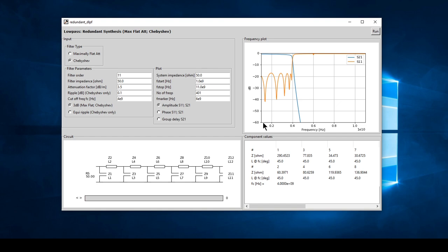You can vary the start and stop frequencies of your frequency plot. In this case it is 1 gigahertz and then stop at 11 gigahertz. The number of frequencies you can increase to get a smoother plot or to increase the accuracy of your marker. And then the marker we can move around. We can make that 4 gigahertz, and the marker would go to 4 gigahertz.